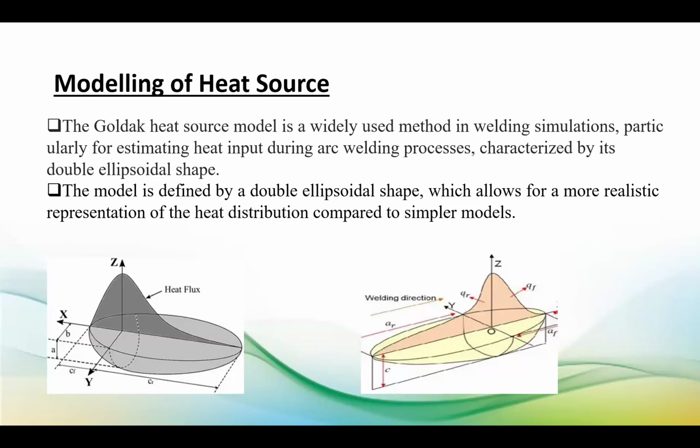This Goldak heat source model's schematic representation is here. There is an equation also. Utilizing that equation, we can create the mathematical model of this welding torch.